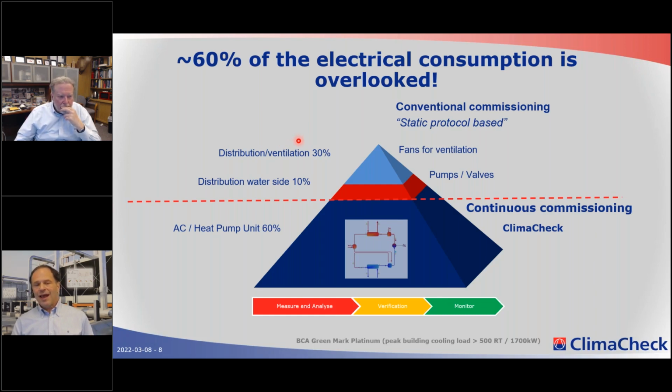I wouldn't say it's always well done, but all systems have some kind of balancing. Then, with today's situation of variable flows, it might not be very efficient to balance before you commission your plant and hope that it's going to be useful for the life of the building.